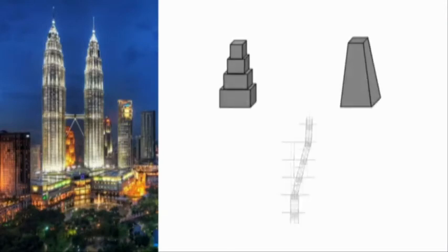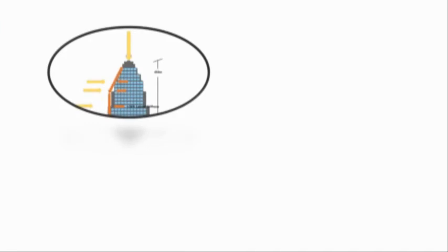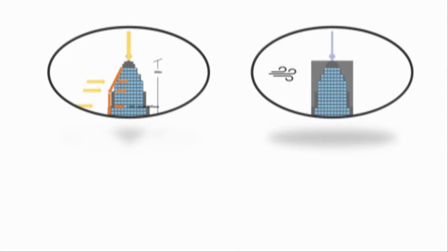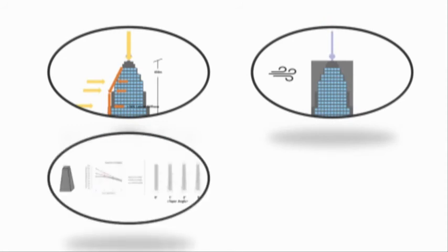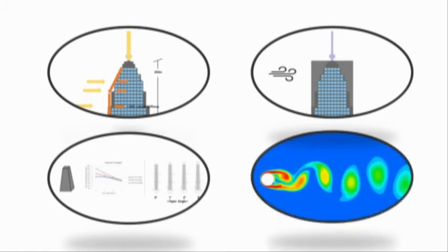To summarize, the upper part of the Petronas Twin Towers kept the setback and tapered shape by using the sloping column. Due to this sloping column, it got more lateral stiffness. The advantages are the decreasing area against wind and the lower lateral displacement. Last, the vortex shedding effect. All of this helps this high-rise building resist very strong wind at higher elevation.